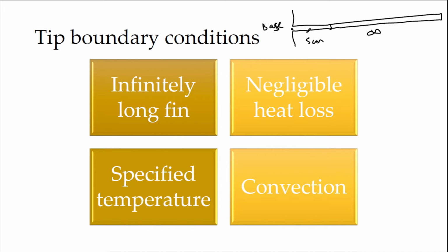So there are cases where, although your fin is 5 cm or whatever length, we assume it to be very long, so that your tip temperature equals your ambient temperature.